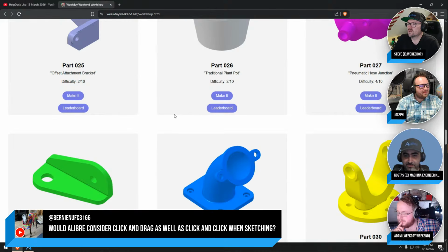Oh, Adam, we're on the same page. So you drag to the right, select everything in the box, drag to the left, select everything that intersects with the box. Some software, instead of clicking and dragging to make these boxes, you can click, and it makes the box.